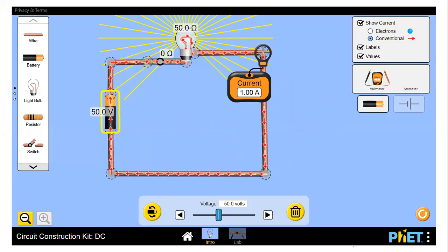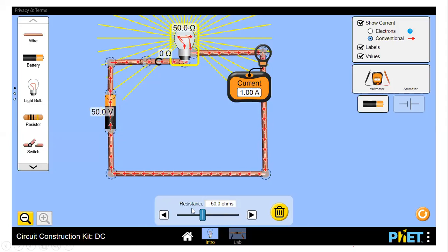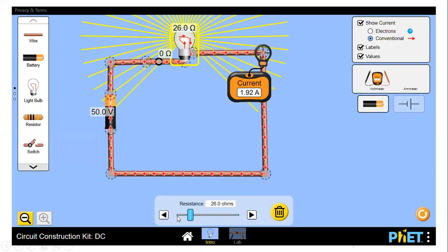So basically your home appliances are current driven devices. It depends on how much resistance it has to offer. Now, if I reduce this resistance, say for example, make this resistance 25, what has happened? See, your current is again 2 ampere. So now it again consumes 2 ampere. So how much will be the energy consumption in this case? Can you find out this?